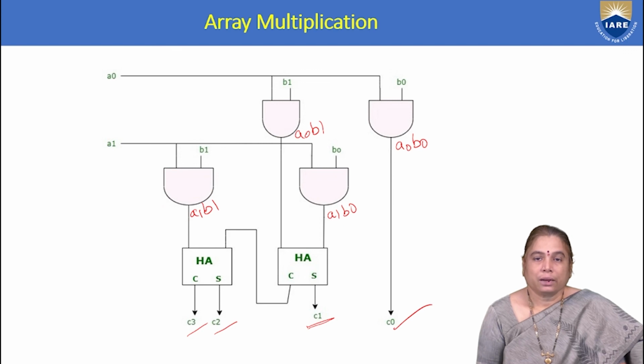After that, with the help of combinational circuits, the addition and multiplication operations can be performed with the help of the array multiplier. The array multiplier consists of AND gates, half adder and full adder circuits to produce the binary multiplication. These are the combinational circuits which help to provide the binary multiplication or the product terms.